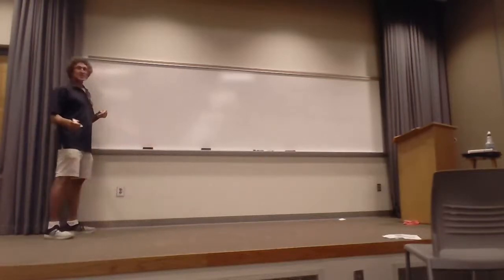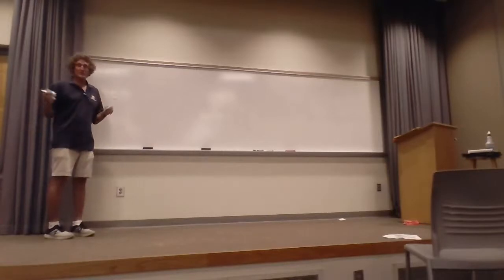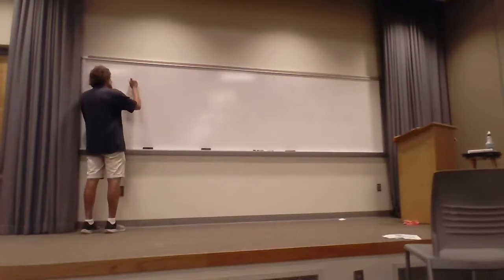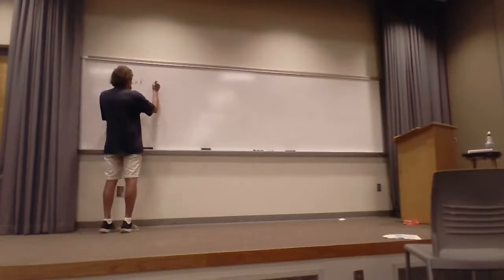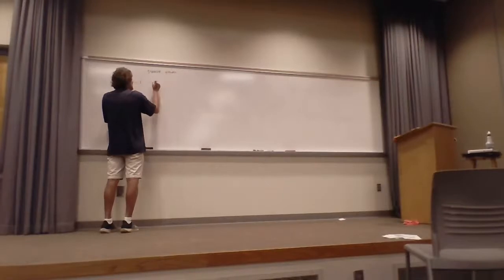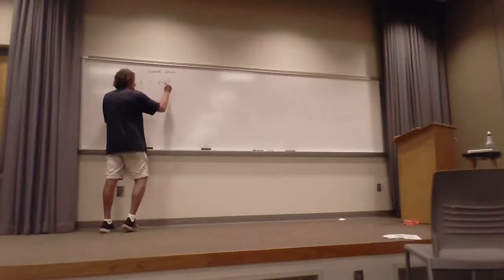So as engineers and physicists, we always start with the fundamentals, the laws that are never broken. And those are Maxwell's equations. So we take the curl of E, and we're going to do this in the phasor domain, is equal to minus j omega mu times H.